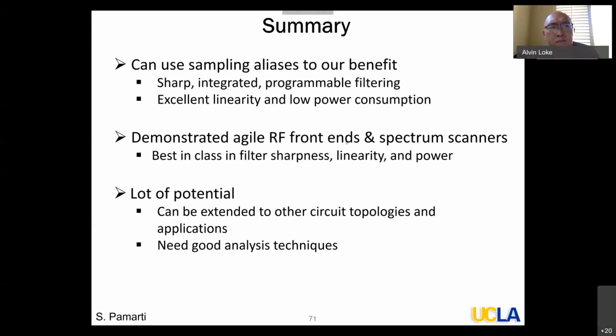While I did not go into detail here, what we did include is a DC calibration of the resistor DAC. All our filters are designed assuming a well-calibrated 10-bit resistor DAC. So we build about a 12 to 13-bit actual implementation, and then we calibrate it one time at DC to get the 10-bit.